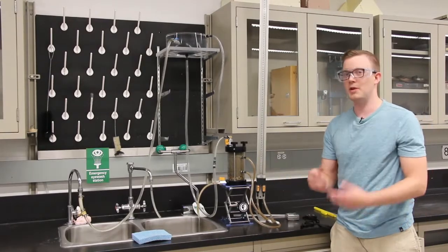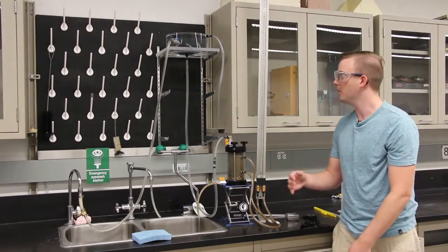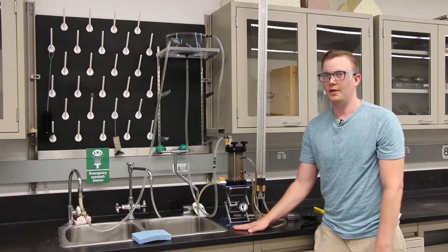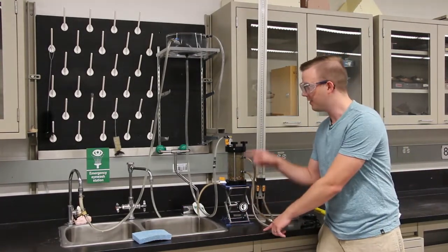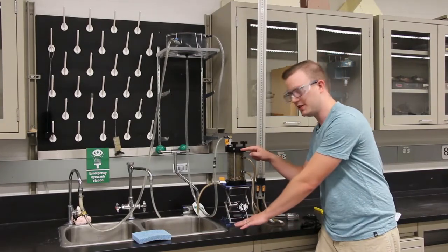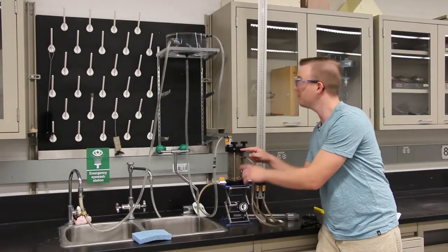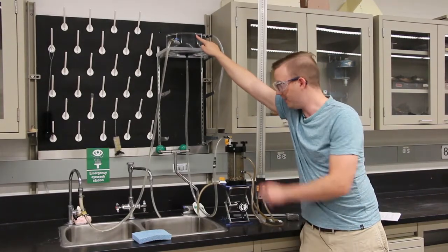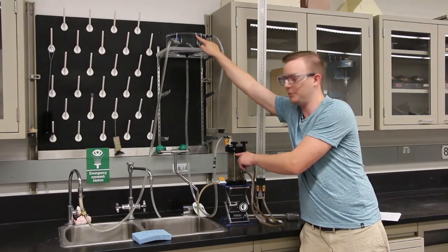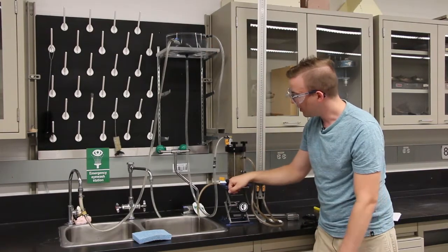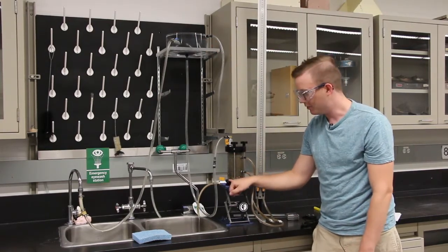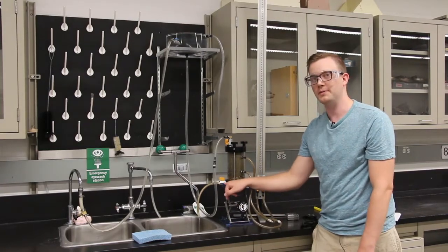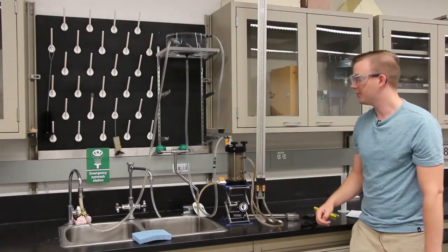When we're measuring for hydraulic gradient, we want to measure from a datum. It'll be the countertop table. The total head at the top of the sample will be the distance from the countertop to the water line here. That's the total head at the top of the sample. For the discharge port, the total head will simply be the distance from the countertop table to that port. And then the head